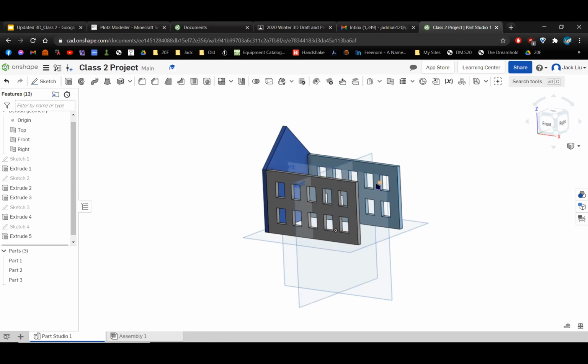We could draw all our lines again and extrude, or we can do a mirror in 3D space, right? So we saw mirrors in 2D, but now we want to do a mirror in 3D space. So the mirror tool, let me find it right here. It's kind of like the 2 L shapes again, but now it's in 3D. So it's kind of in the middle of your toolbar, right here for me, mirror.